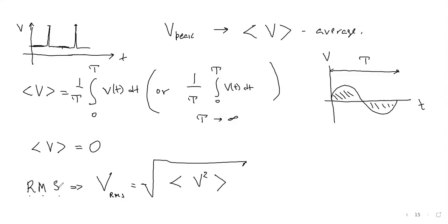And maybe we can calculate this RMS value for a harmonic signal right now, and we can relate the RMS value and the peak value, and see if you have this 120 volt, 60 Hz signal, then 120 is RMS. And in most cases, you're given RMS values. You practically never know the peak value of your signal, but you can calculate this. Okay, let's calculate it. It's not a big deal. So let's find this.